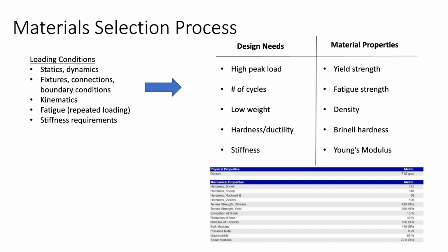There are some cases where you actually want less stiffness. As Robert knows, the blade for the suspension last year was a way of adjusting the roll stiffness of the car. So in some instances, you want to be able to actually have a lower stiffness than a higher one. So all of these unique design needs should be identified before you even go to the material selection phase. So in terms of needs, how do you actually express this as a material need?